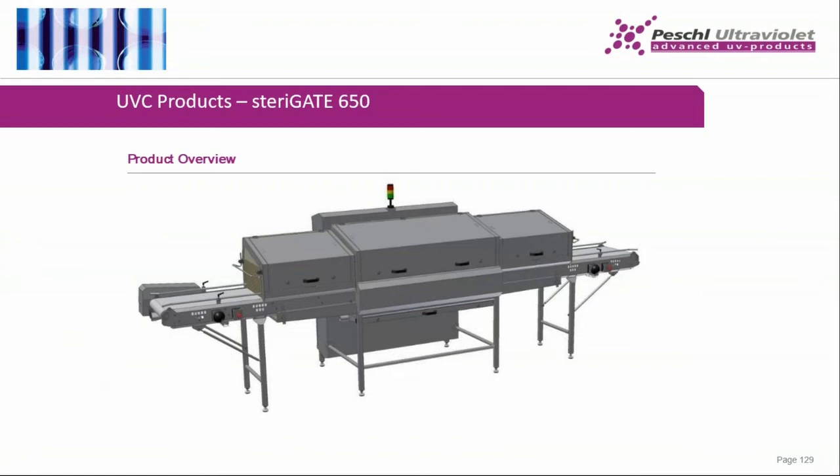There you can see the inlet of the tunnel. This is a zone where we need to make sure nobody will be irradiated, because this middle part is the place where the UV lamps are placed. And these UV lamps have really high power, and this high power cannot go outside, and therefore we need a really safe process. We have these 2 parts, inlet and outlet, where we protect against the UV radiation when employees stand in front of the machine.